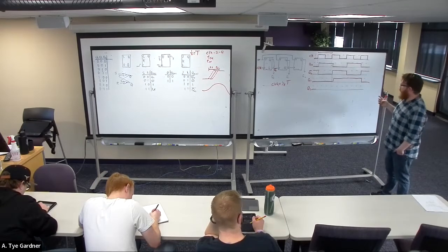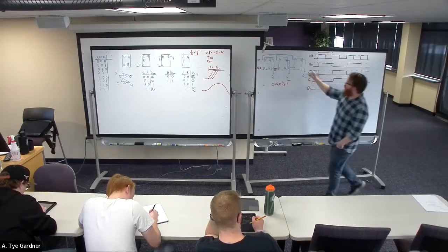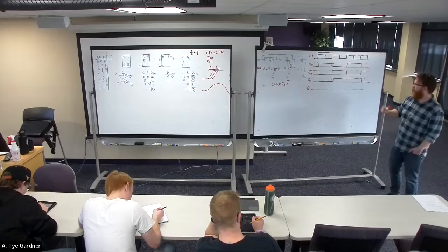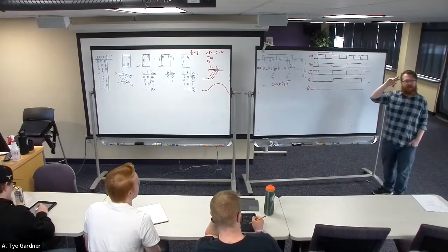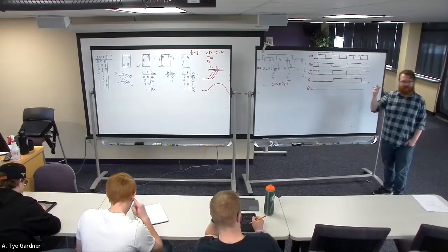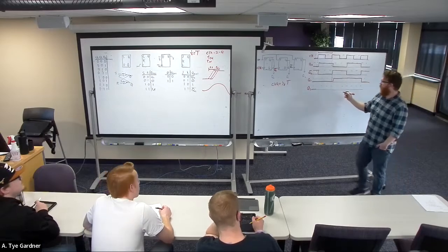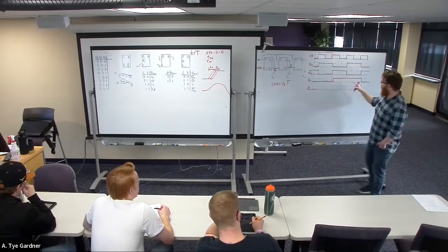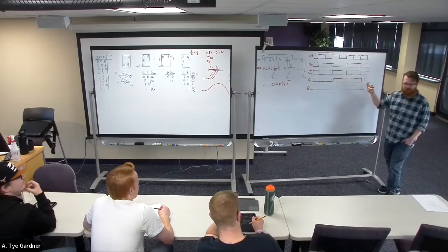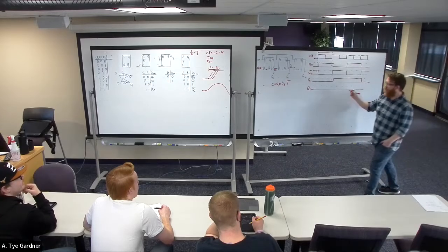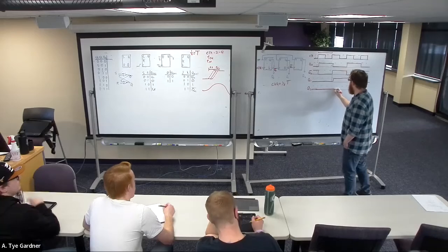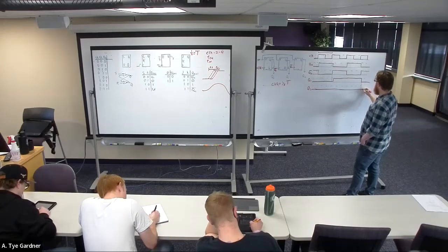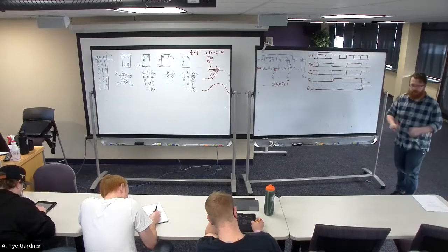Well, what this means is because we're using Q1 bar as the next one's clock, this is Q1. We can't in our head imagine what Q1 bar looks like, right? It's the inverse of this, meaning Q2 doesn't do anything, it doesn't react on this rising edge. It reacts on this falling edge because we're looking at the inverse of this, right? So that means that Q2 follows along until this happens. A little bit of that delay, rising edge.